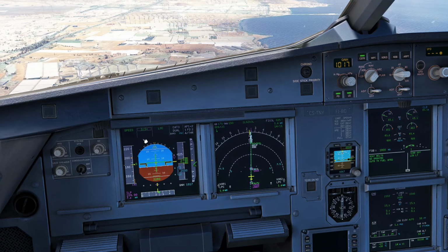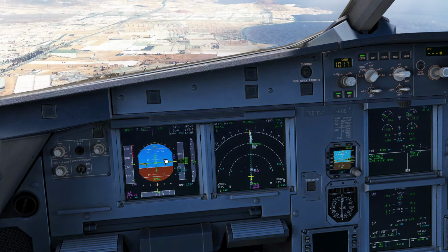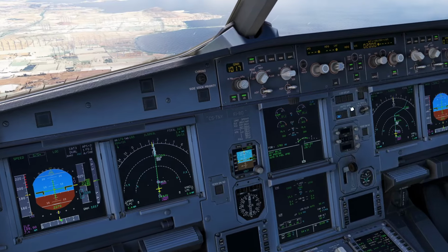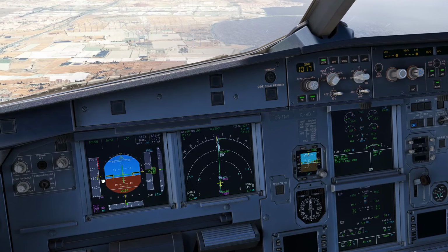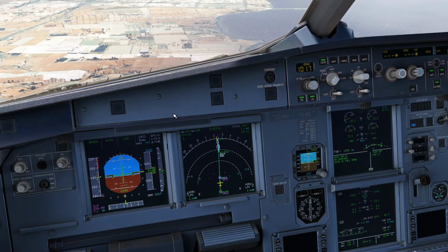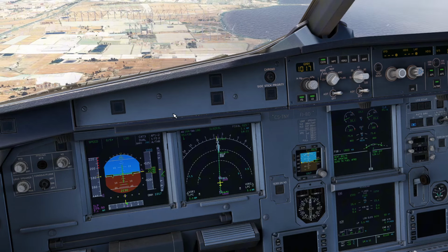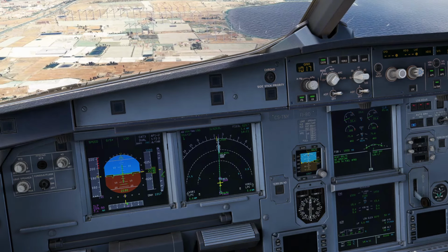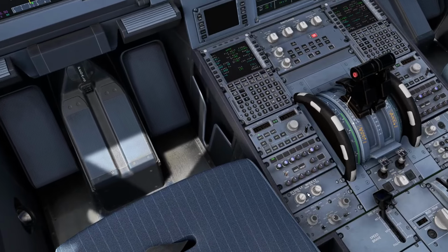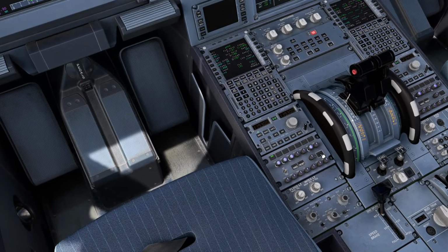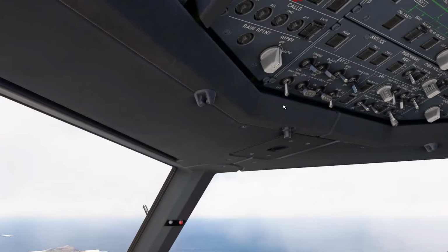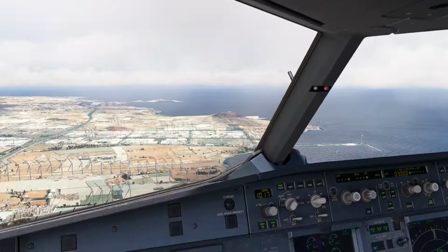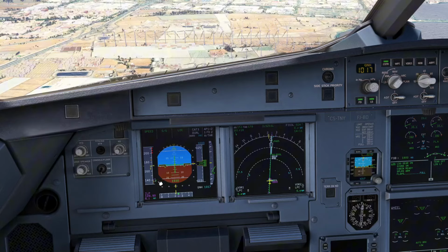Okay. Glide slope, GS star, flaps 2, speed check, flaps 2, approach altitude 3000 is set, and aircraft decelerating to F speed. Okay, gear down, speed check, gear down. Cabin crew, prepare for landing. Landing clearance received. Aircraft decelerating toward the F speed.